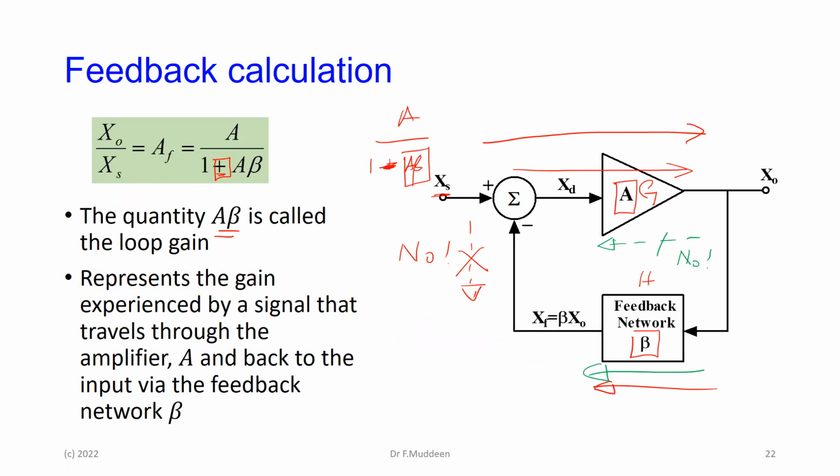Some different topics in a way. We covered some of them without knowing it before, but we try to put a name to what we've met before, the particular types of amplifiers. So your takeaway here is that there are 4 types of amplifiers, depending on whether you're amplifying voltage or current, and whether the input and output is a voltage or a current. There are also 4 ways that you could supply negative feedback to that, depending on if you're sensing voltage or current and feeding back voltage or current. If you're sensing voltage, then the type of feedback is going to be voltage something feedback. If you're feeding back voltage, it's series. If you're feeding back current, it's shunt feedback, because the current has to feed back in parallel with the input. Okay?